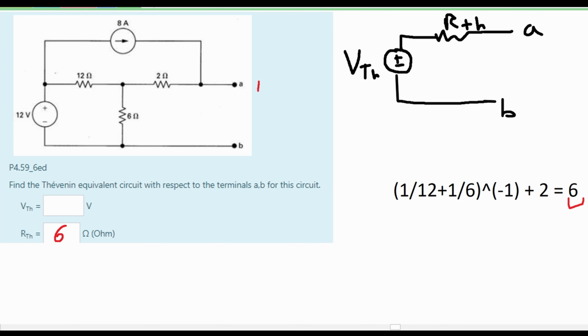The voltage is going to be going across our A and B terminals, and we need to find what that is. There's a couple different ways we can do this. One I like to do, what looks good here, would be a node voltage analysis. We learned about this earlier in the chapter, where basically we pick 2 nodes, this one and this one. I'll pick these 2, and then we set up a current formula and then find the voltage.